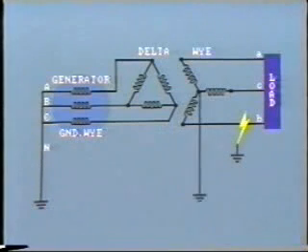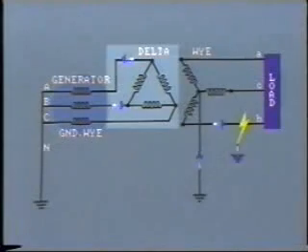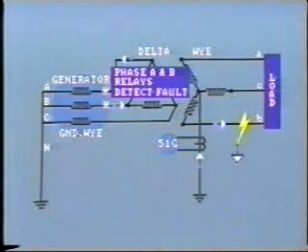With the Y side grounded, ground fault current would flow in the faulted phase of the Y winding and would be transformed into the delta winding as shown. Note that the phase to ground fault on the Y side manifests itself as a phase-to-phase fault from the delta side. Thus, generator phase A and phase B relays could detect the fault, as could an overcurrent relay in the